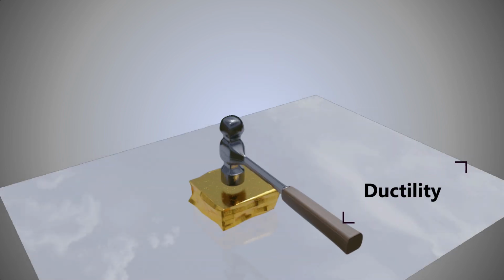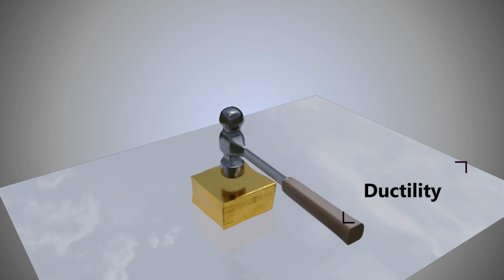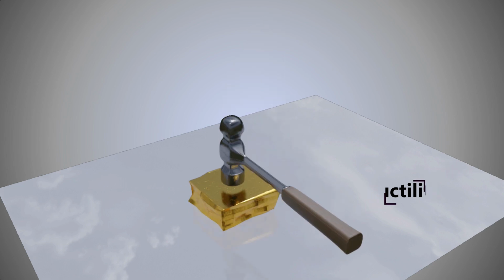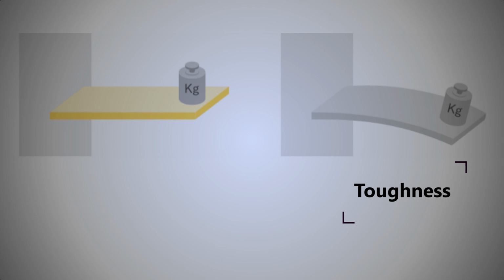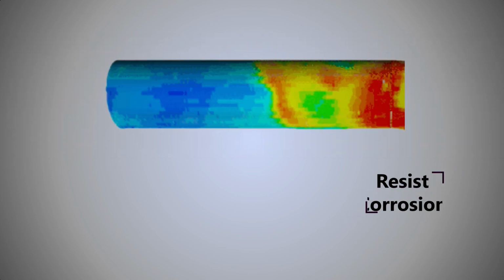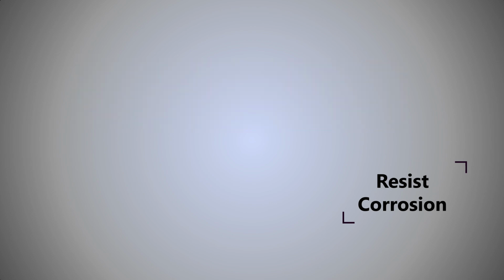Ductility is also critical. Ductile steel can deform without cracking, which is essential during running operations, especially in deviated or horizontal wells. Toughness allows the casing to resist sudden impacts and brittle fracture, especially in low temperature or high stress conditions. Depending on the environment, casing steel may also need to resist corrosion from CO2, H2S, or saline formation fluids. In such cases, special alloy steels or corrosion-resistant grades are used.